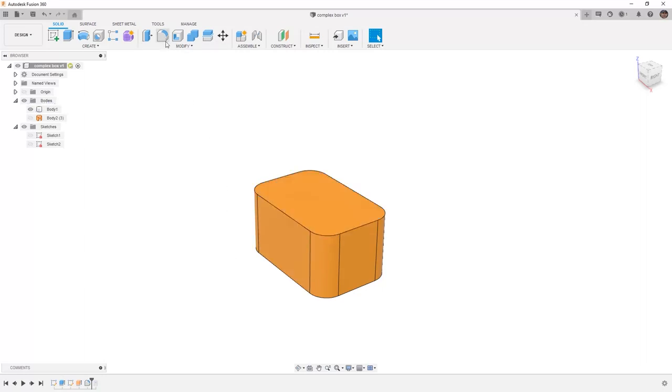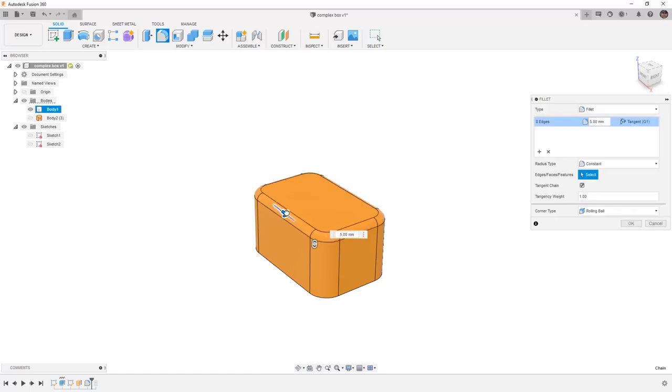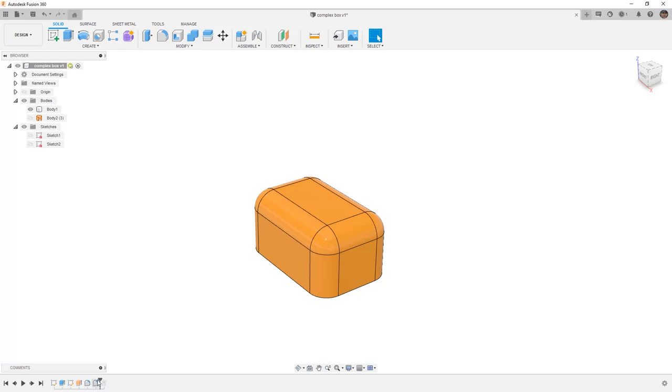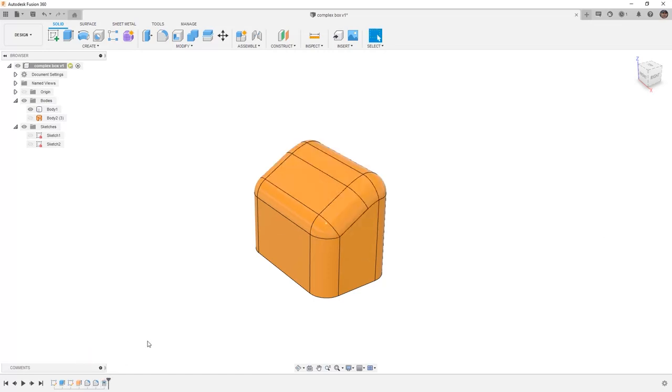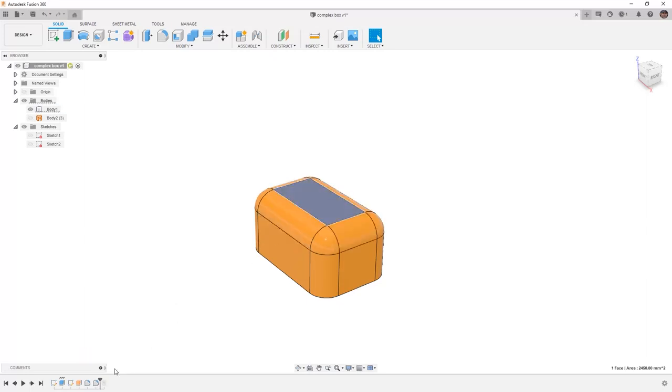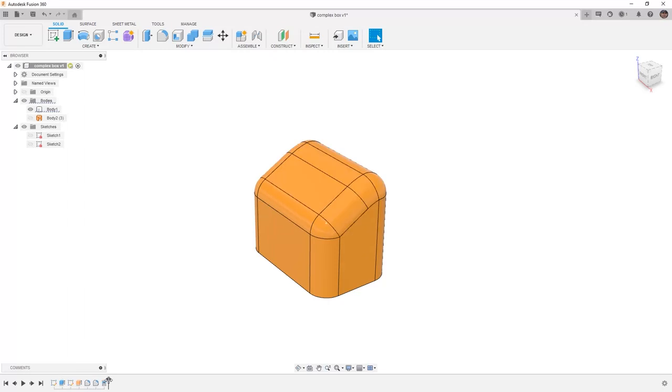Even though we've rounded the corners off, that selection is still there. But what happens if we add a fillet to the upper edge? In this case, I'll add another large fillet, 15 millimeters, say OK, and let's roll this back. Well, Fusion was still able to extend that. Because there was still a single face selection in the center, it was able to bring that geometry up, including the fillet. So it carried the fillet and it propagated around the new replaced face.